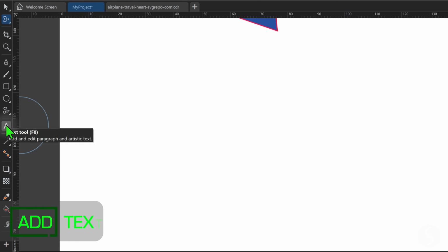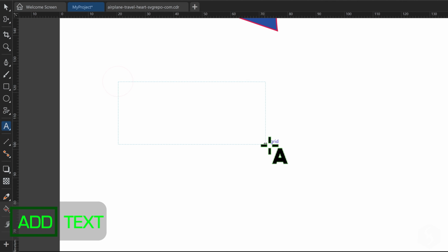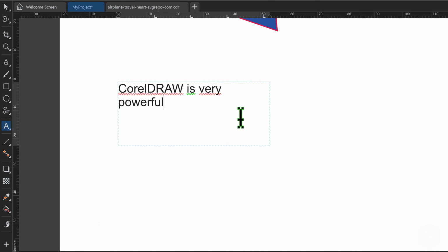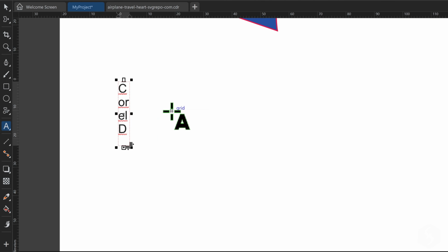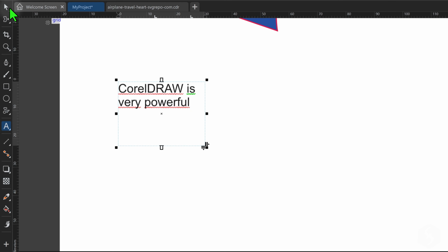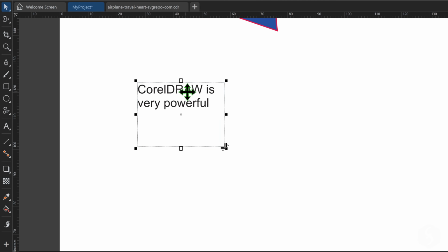Enable the Text tool on the left and click and drag to place any piece of text. Extend the text box through its black nodes and rearrange the text or show the entire content in case the box turns red. Use the Pick tool to select the text box, move it on the canvas as you like, and double-click on it to continue typing.